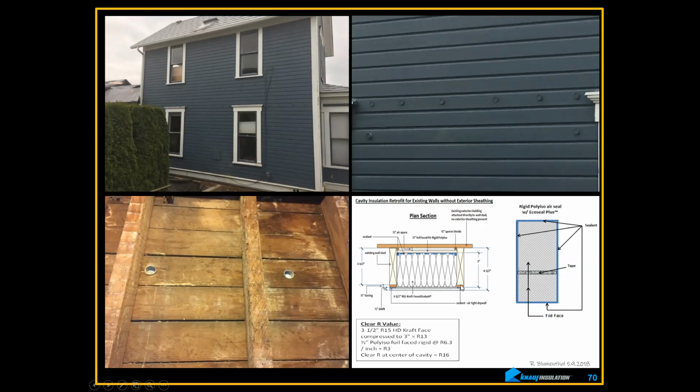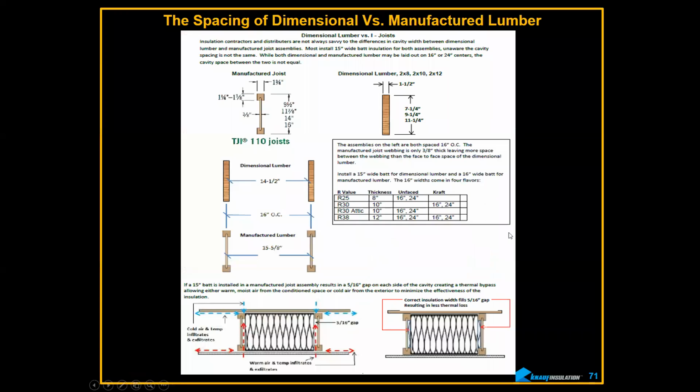This shim space here allowed me to do the half inch in here, because it's still a 2x4 wall. We just projected it out a little bit and matched it up so you could put drywall on it and not have the 3/4 of an inch thickness of plaster. And what will we get? We get an R16 cavity out of the deal. Not too bad. So that's the way you can do that.